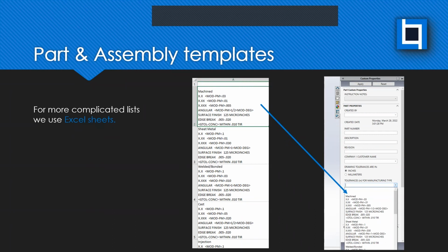And that's also kind of a catch, because if you don't fill out your custom properties, or you have a new person who comes in and creates a part and says, all right, it's done, ready for the drawing, and then you drag it and drop it in, your title block's going to be blank. So it's a good catch to ensure they went through and filled those out. You can say, okay, you didn't fill out anything, you need to go back in and fill those out. So again, just adding the blank ensures that it doesn't default to any. Those are little tricks that we learned along the way.